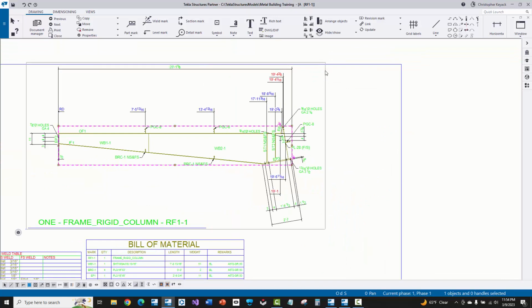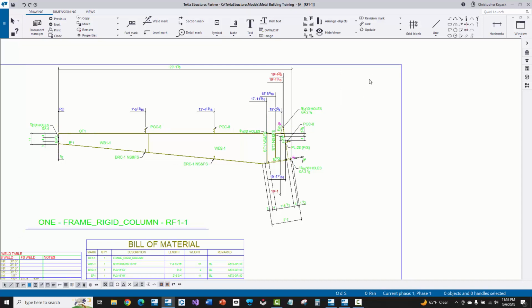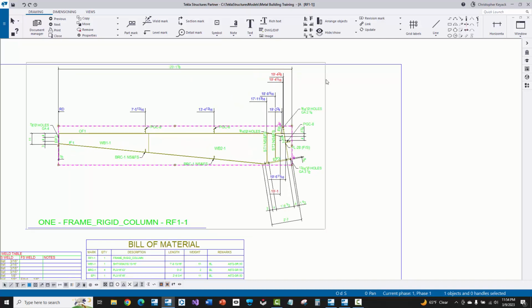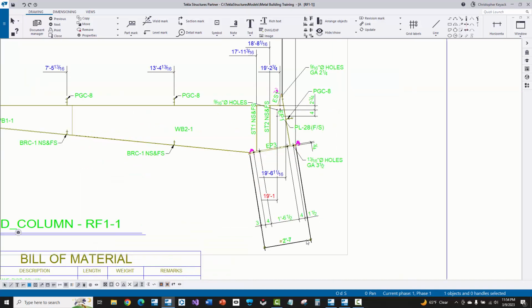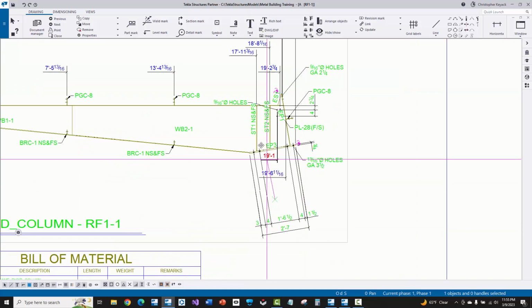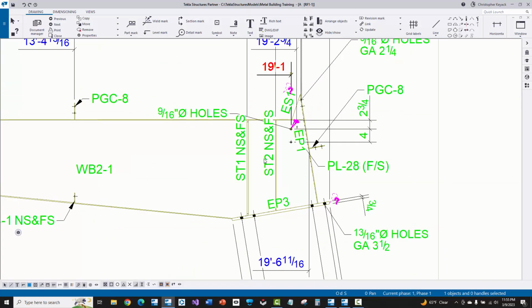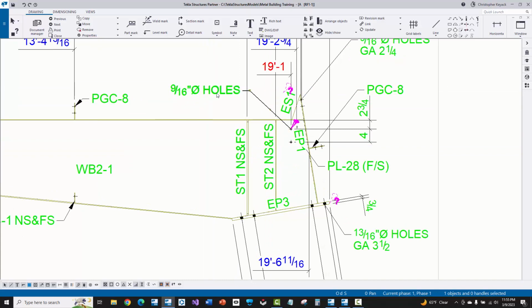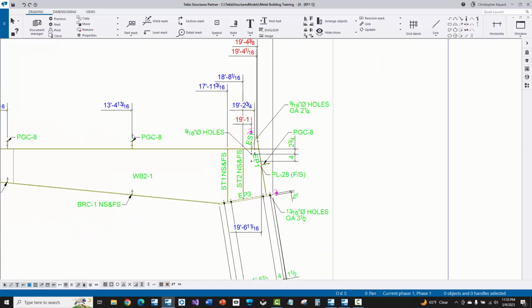And then if you click on the gray border, you can manually move that, or you can click on the background of the drawing and say Arrange Drawing Views, and it will try to auto scale and fit that in there. Now I'm going to undo that because I actually liked how it was stretched out a little bit, so I'll just move that around. I can decrease these dimensions. I can move that running dimension up. So you pretty much have full control of dragging and dropping and manipulating and moving things around so that they're cleaned up.